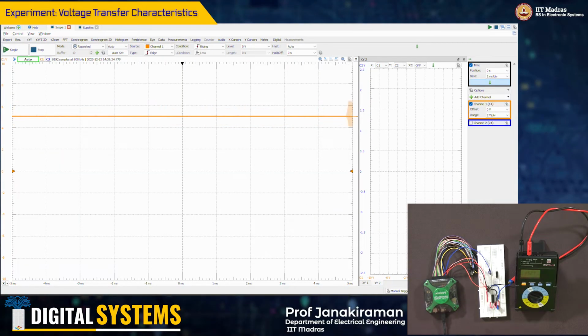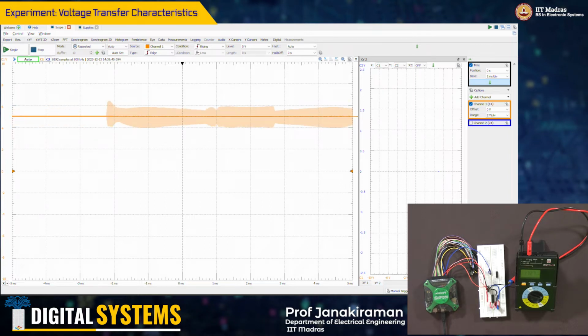So, if I look at this, what you see here is the orange color line, and you must focus on the y axis in orange on the left, which is channel 1. It says in volts. Currently the output voltage is reading a DC value. There is some noise, but it is reading a value of 5 volt.